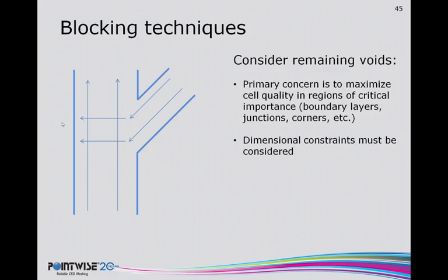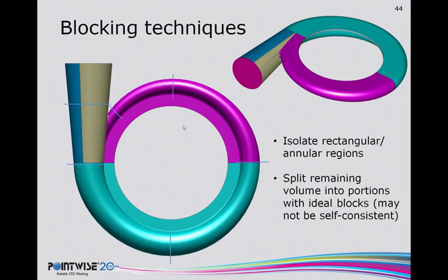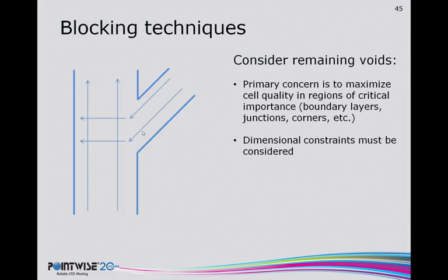The problem is, whenever you do a topology like this, you can think about it and you can say, all right, well, that's possibly going to work. But for instance, in this case, because the cross-sectional area of the scroll at this point and near the outlet here is such a disparate scale, we're really going to need a different topology. That's not going to work, and additionally, that's not going to allow us to resolve these feature lines in the model that we really want to keep. And then also you can weigh in dimensional constraints, etc. And that may rule out a couple of your topologies.